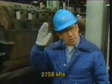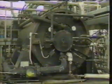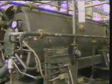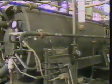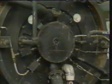Now let's look at the vertically split casing. Vertically split casings are used in most single-stage and higher pressure multi-stage applications. The design of the vertical split reduces the wall thickness needed to confine the high pressure gas, and the smaller seams at the end plate allow for easier sealing. There are several vertically split configurations.